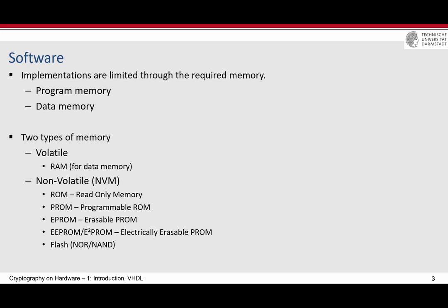Now, I have to explain that most of the FPGAs that we are dealing with are SRAM-based FPGAs. SRAM means static RAM, which means that every time the FPGA powers up, everything which is in the configuration memory of the FPGA is gone, and the FPGA has to be reconfigured after every power up. There are a few flash-based FPGAs that we are not working with in this lecture. They are mainly for military applications, which means that the FPGA configuration is inside the FPGA and it doesn't need to be reconfigured after power up.